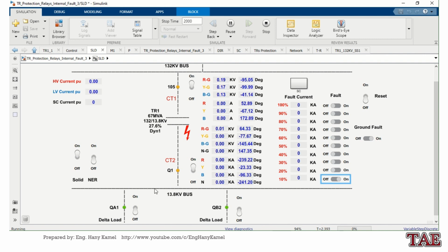You can see the protection operated and tripped the transformer, with force reset. The current in blue phase, because this one is connected between H1 and H3 for R and blue, is very high, also in R phase. So differential is expected to operate.